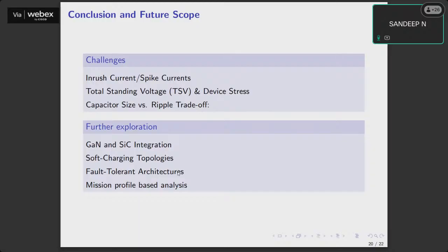So a structure should be designed with some flexibility. When you're building an inverter, it should have some flexibility, especially multi-level, that in the event of a fault, for example, a switch open circuit or a short circuit path, there should be some fault handling mechanism that should take care, and it has to reconfigure the structure so that if not 5 level, the inverter should at least go for a 3 level operation, or even in the worst case, go for a 2 level operation. That is your bipolar kind of operation. Okay. So those are more attractive, right?